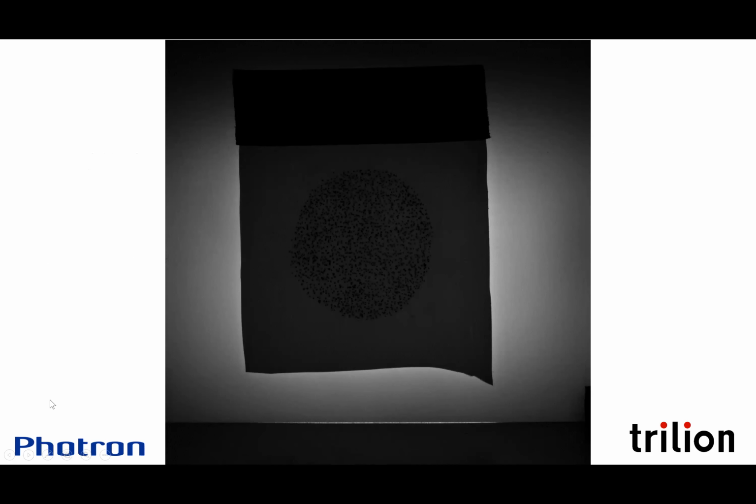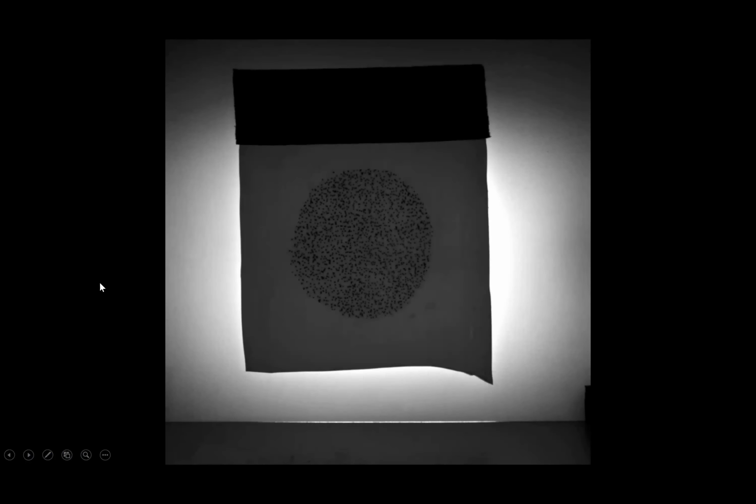And so here's just a very simple example, all right? So we have a speckle pattern here with just a fluctuating backlight. I'm sure Tim looks at this speckle pattern and is disgusted because it's just something that we're playing around with. But don't worry necessarily. So we got this area on the outside of our rubber material with the pattern on it. We're not really concerned about the saturation there. We could have used dual slope shutter to get rid of that.